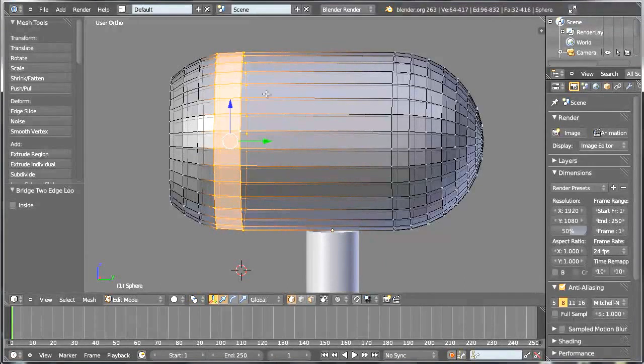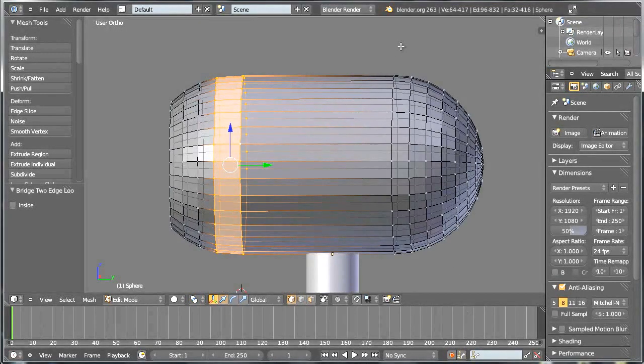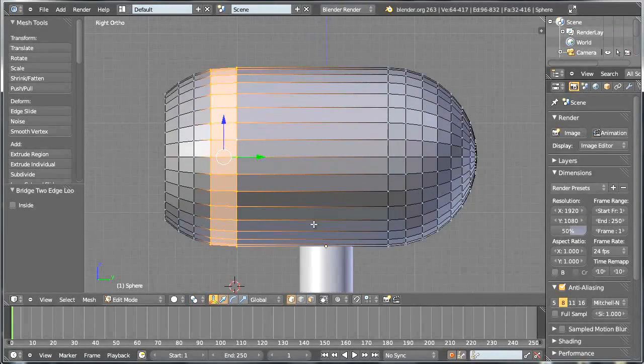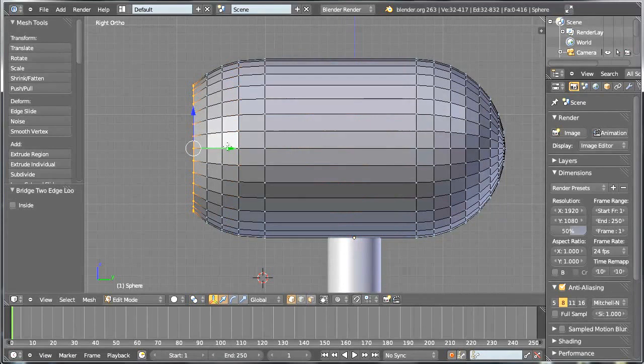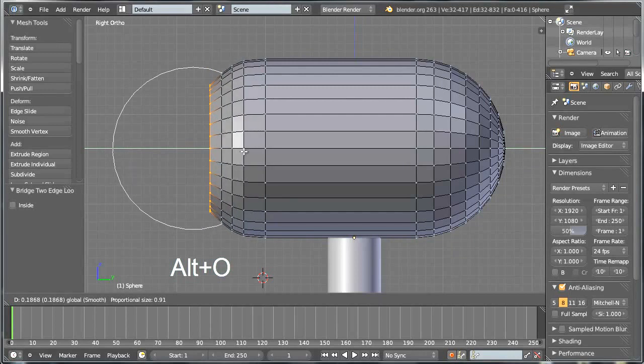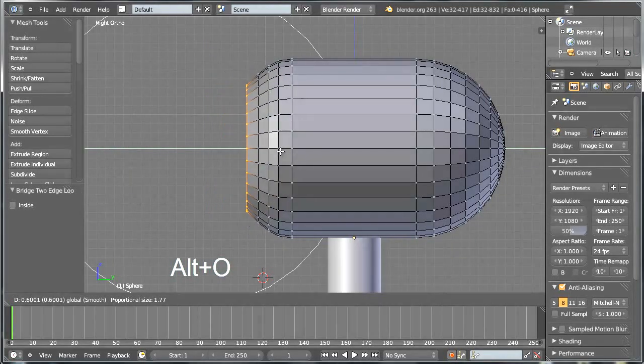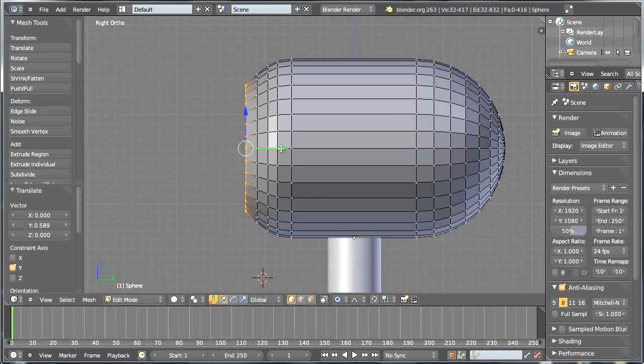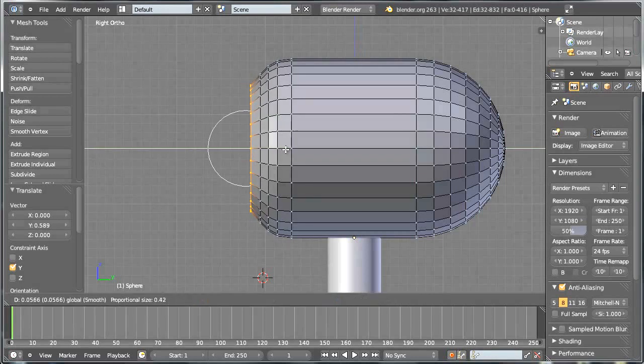By reusing parts of the mesh, you can save time sometimes when it comes to modeling. So we could always, of course, press Alt O, enable the proportional falloff, and just move it a little bit, something like that perhaps, and even better. Well, we can. All right.